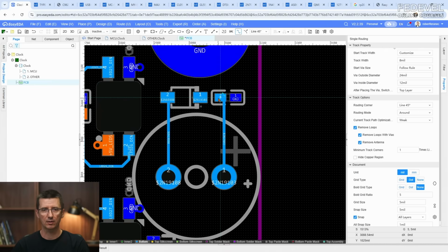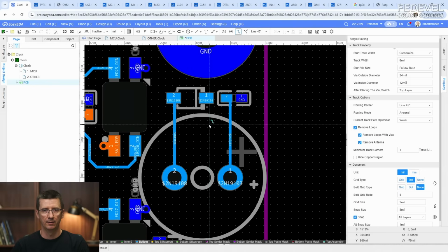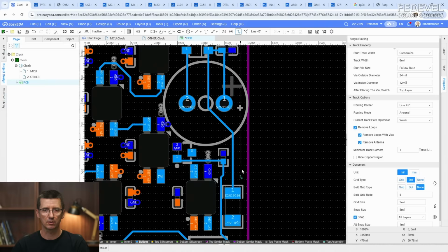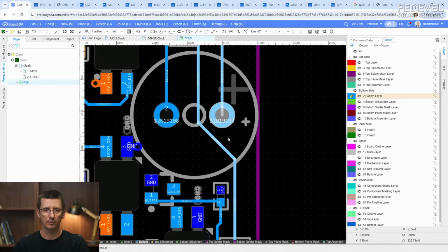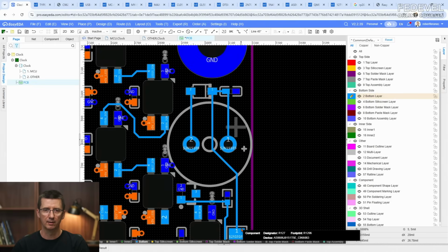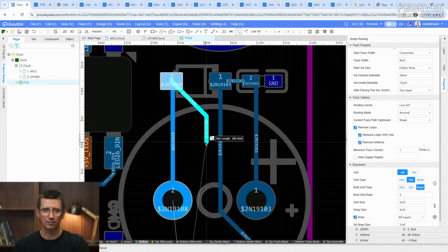So I did a direct connection with the diode. And now I will go down here. So this may be a little bit unusual routing. Notice I could connect it directly here, but I went to the diode and then down, because the diode is there for some kind of protection and we don't want the signal spread to the rest of the PCB.